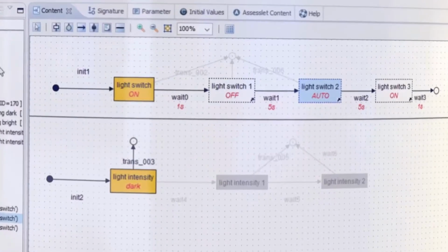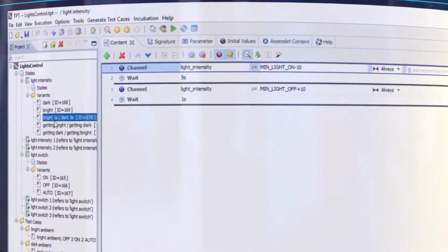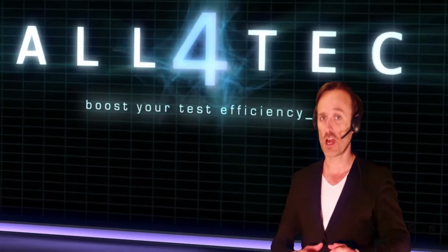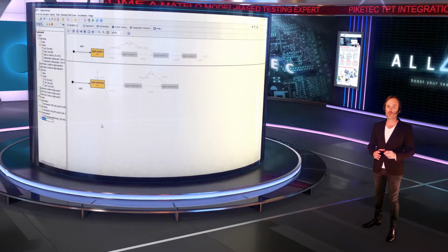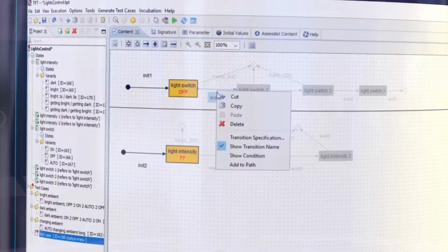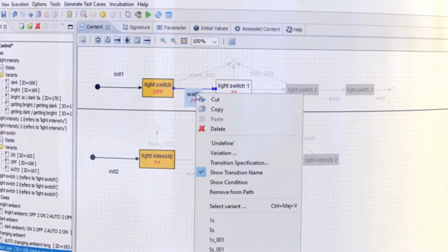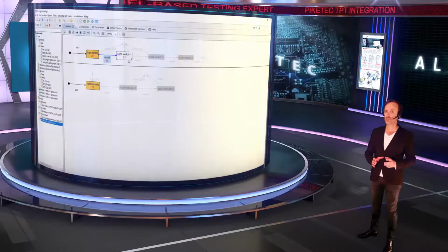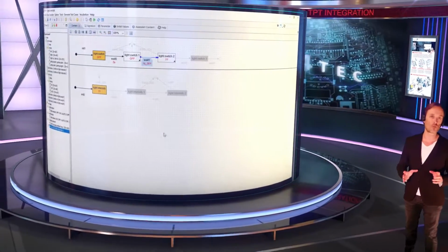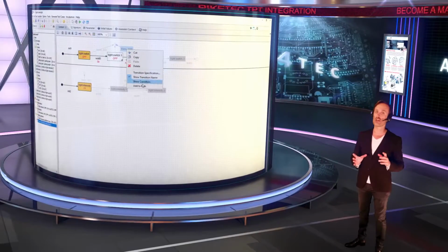The TPT project is composed of states and transitions, where we can set the list of possible behaviors as variants, which are temporal signals. If you want to create test cases in TPT, you need to manually add transitions to pass, and assign on each transition or state the variant to use. The aim of the TPT MaTeLo plugin is to automatically create test cases into TPT with a specific strategy approach and minimum effort. Let's see in detail how to create TPT test cases with MaTeLo.